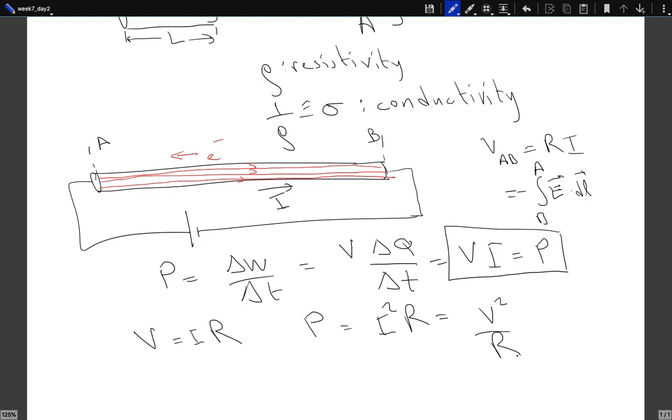One more thing, we said that this resistivity actually depends on the temperature. It's one plus alpha times T minus T0. You can write that with temperature it will change. And if you know the resistivity of a material at a given reference temperature T0, at temperatures close to that, you can just write the change like this, where this alpha is the known coefficient based on the material.